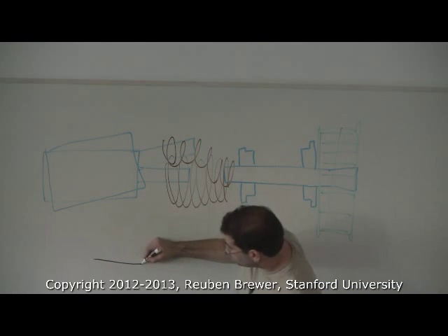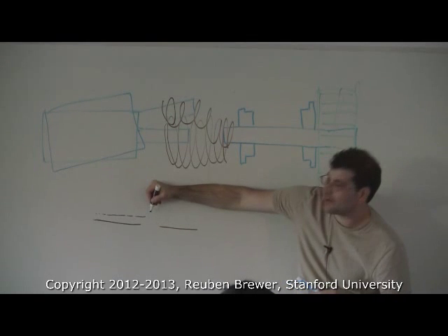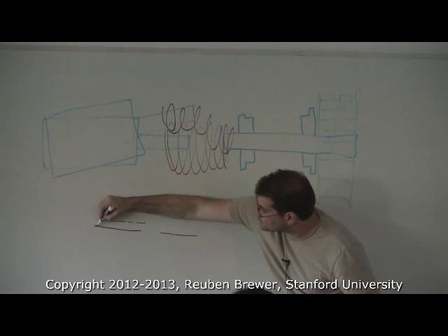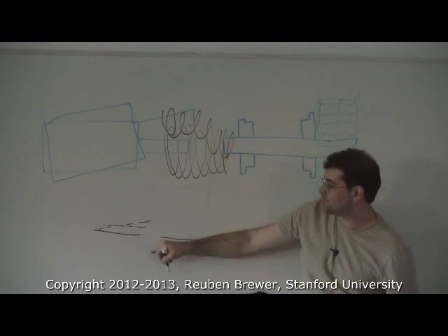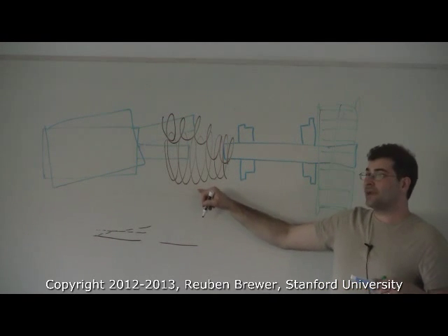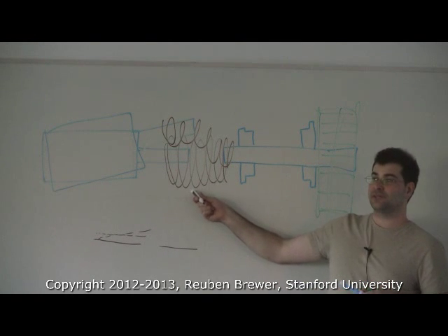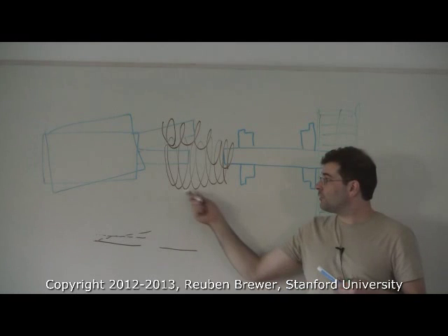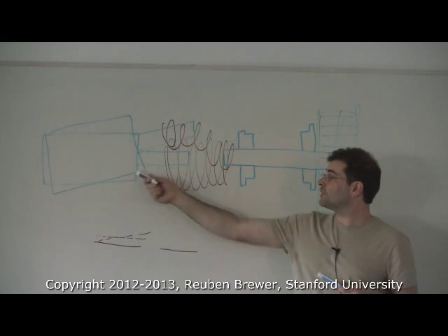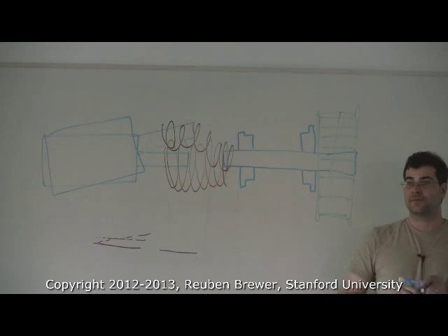So if this is my axis, not only can I move it up, so I have axial misalignment that way, I can also cock it at an angle, and that misalignment gets taken up in the helical thing. Now, it won't break this within certain bounds because that's what this does. This is designed to do that. If you don't have this and you were to simply put the motor and weld it directly, it would kill your motor in about 5 minutes.